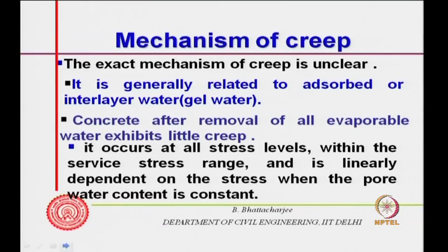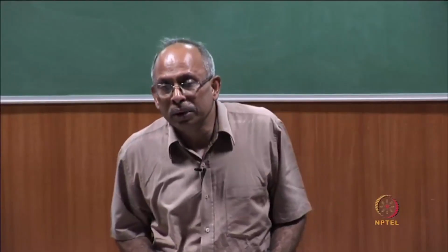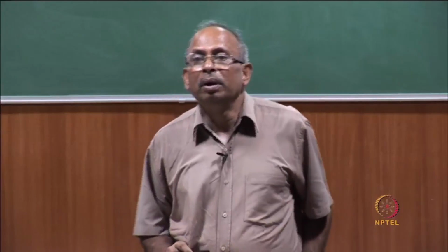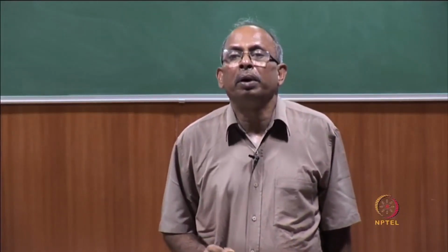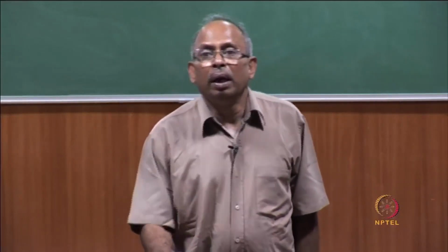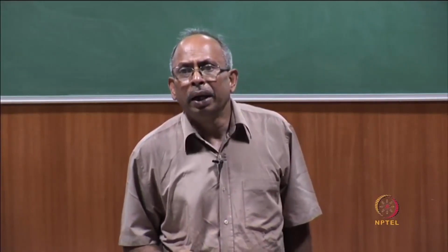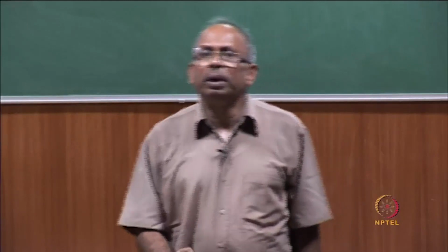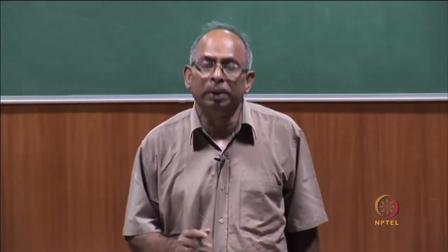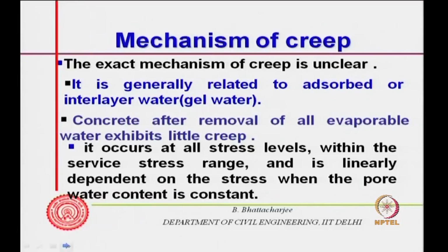As I said earlier, it occurs at all stress levels within the service stress range, that means before failure, and it has been observed that it is linearly dependent on the stress when the pore water content is constant. If you are not allowing it to dry, then it is linearly related to the stress level. So, there is something to the pore water level. If you remove water, then you do not get creep really. Therefore, it is related to adsorbed or interlayer water present in the cement hydrate system, that can be understood.